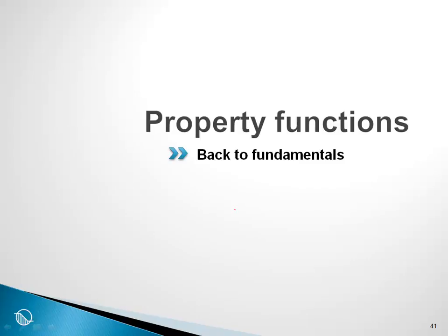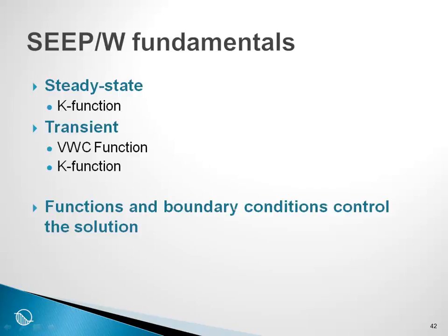Hopefully this will increase your confidence a little bit in selecting proper property functions and when you should worry about defining the property functions in great detail. Once again, it depends on the fundamentals. It depends on whether we are doing a steady state analysis. Obviously, if we are going to do a steady state analysis, then all we need is the conductivity function.